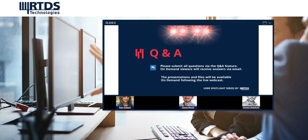But for some specific applications like frequency response tests, we found that to be sufficient. So that's why we adopted that. What we have done is lay out all the transfer functions of that MG set. It ended up as a very high order dynamic system, and then we have to do some careful tuning in the controller gains and also the parameters in order to make sure the whole system is stable.